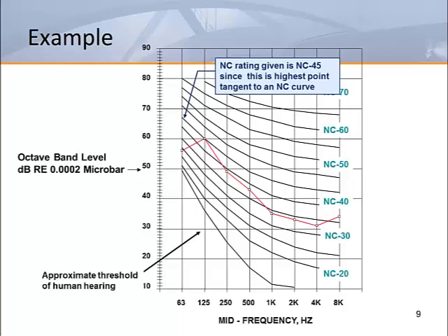Obviously, the 2nd octave band is the critical band that sets the NC level for the space. The higher frequencies just trail off and are of little consequence. Any manufacturer developing a fan-powered product knows that the lower the sound level is in the 2nd octave band, the better the product will be.